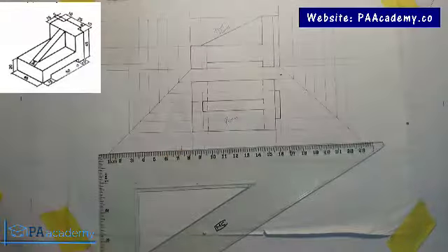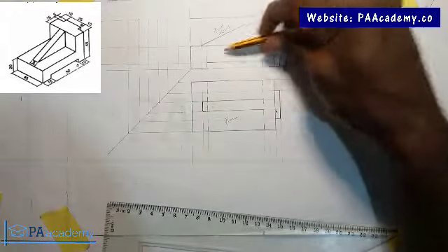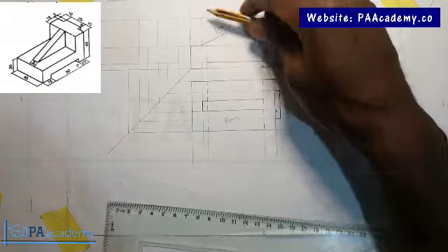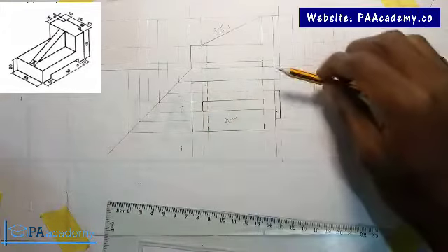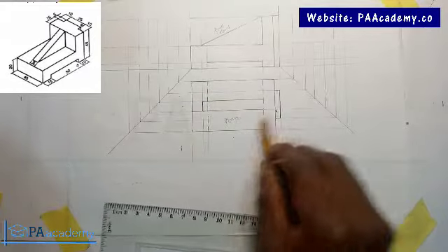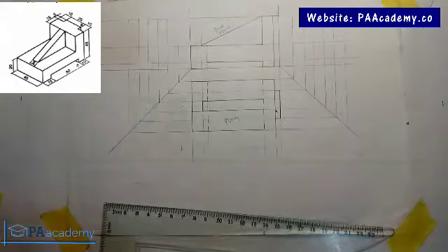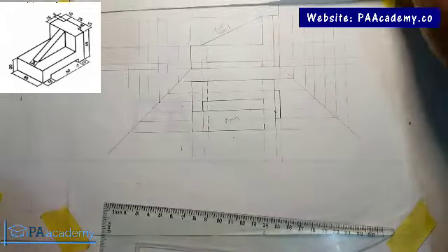So that's the essence of making sure that all your projections, right from when you finish drawing your front elevation, remember those lines are going to project downward. It's the same lines you are going to use to draw your plan, and you're also going to project it horizontally before you project it vertically again. So you can see that consistency is very important. If not, you mix everything up. So now let's draw the side view.